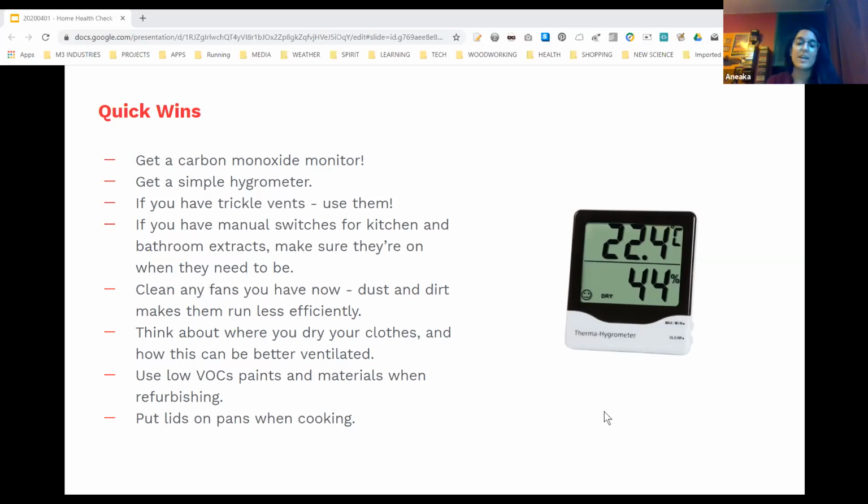So in these homes in particular, the biggest source of heat loss were drafts. So things like draft proofing might have a bigger impact. Well, they do have a bigger impact in the flat that I'm in at the moment because of the particularities of this flat. It used to be that the heating system was coal fires, so they have big air vents in the walls, but now they've been converted to central heating, and lots of those big brick air vents in the walls haven't been blocked up. So you end up getting lots of drafts coming through. But that's just this particular flat.